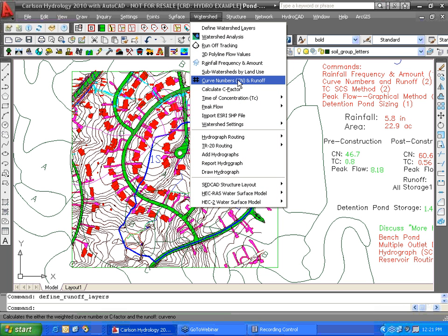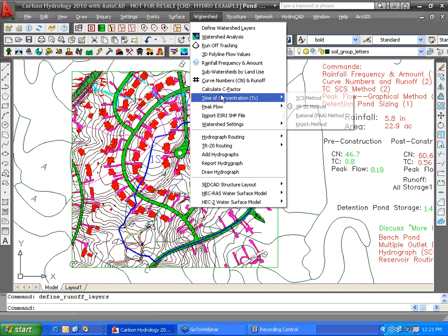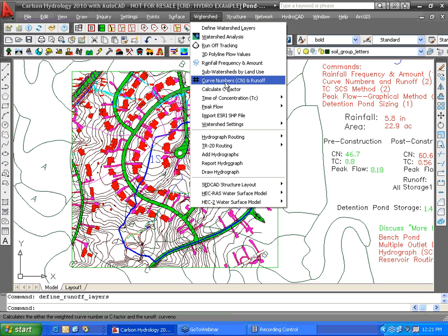Now, it would be difficult to do the existing and the final in the same drawing because it actually finds all frozen layers. So if I wanted to do the existing, instead of that pick one at a time approach you saw earlier and just had one big perimeter for the woods, I would have to have that in a separate position moved over to different coordinates or in a separate drawing, because it will find all layers thawed or frozen when it does this process. I only have the layers for my design working right now, so I repeat that command.